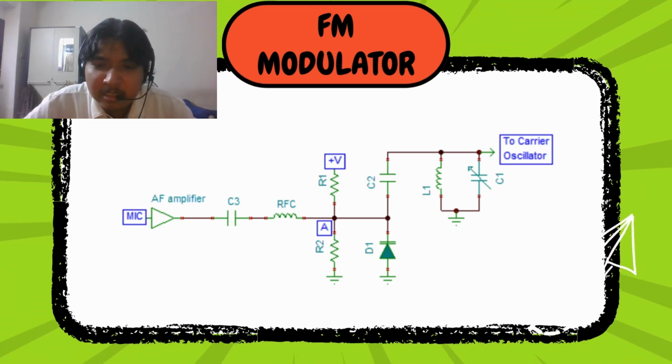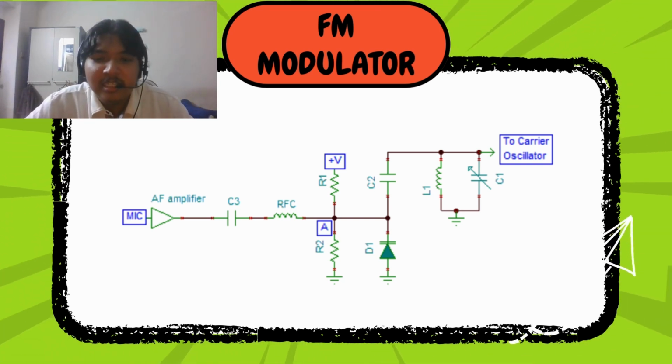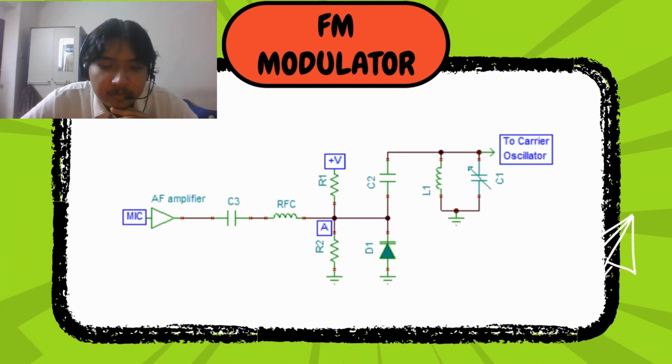Basically, the capacitance will change based on the applied voltage, meaning that it can be tuned in the VCO circuit, and when the message signal is applied, the frequency of the circuit will change according to the message signal.